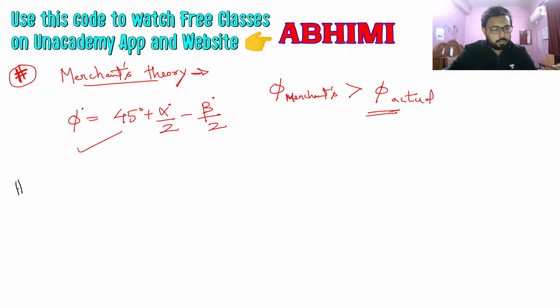So Taylor's tool life equation, that is also very much an easy formula. That is V T raised to power n is equal to C. And remember here, the most important thing is that V is always in meter per minute and T is in minute.